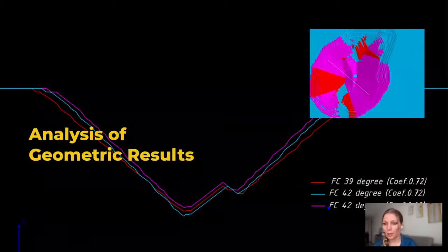For an inclination angle of 42 degrees, shells with coefficient 0.72 and 0.68 are nearly parallel. However, the shell with a coefficient of 0.72 is deeper throughout the gap, indicating that more rocks will be extracted, which is also logical. Nevertheless, the key issue remains with the numerical expression of these indicators. Even minor discrepancies over broad areas may result in significant variations in volume.